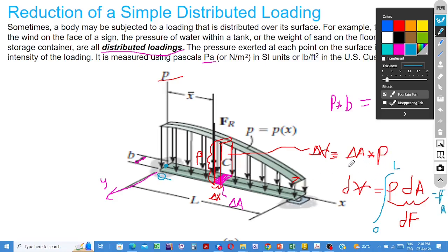But it is also equal to the volume under the load curve. If we know the surface pressure, just by finding the volume of the space under the load diagram, we can consider the result as the magnitude of the resultant of the distributed load.